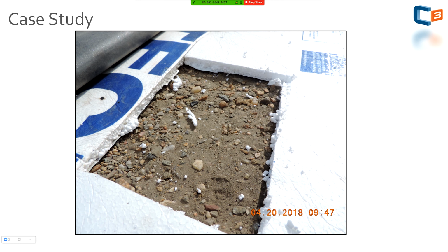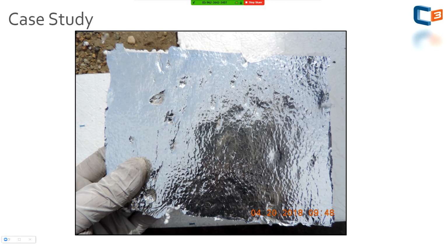A lot of times EPS products, some of them are about a 1/4 inch to 1/2 inch thick, and they have a plastic facer on one side or both, or varying facer types. And it's really just meant to fill in the voids of the ballast they can't remove on the built-up, to just allow a smooth, consistent surface for that EPDM membrane or whatever they're overlaying it with. What was difficult about this was it had a foil facer on the bottom side. This is for thermal reflectivity.